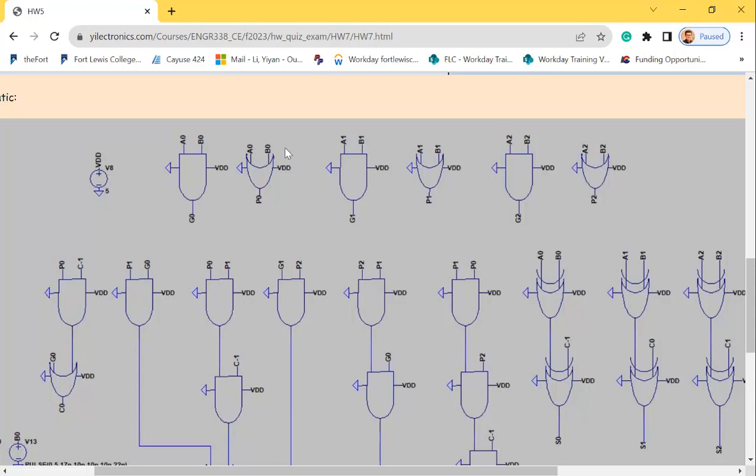These are inputs to the adder. We know they are there, right? We don't have to wait. Since A's and B's are available at the very beginning, we can directly find out G's and P's by just passing these inputs through one gate instead of multiple stages. So the delay from A's and B's to G's and P's is just one gate level, or one stage delay.